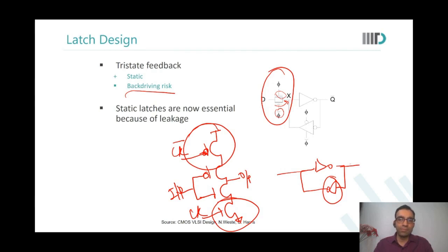Sir, this type of latch that you have drawn, back-to-back inverters, we use in the SRAM cell, where we largely ignore the diffusion input problems, and I'm driving a pass gate in the SRAM cell. So SRAM cell is a different thing. We will look at it when we cover that topic. SRAM cell is never driven by a system input. It is always driven by something within your control as a circuit designer, so you can always characterize it and manage it. I know what is in the proximity of the cell and what the loads are. SRAM cell is used in a very controlled environment, so we can do it over there. We cannot do it elsewhere.